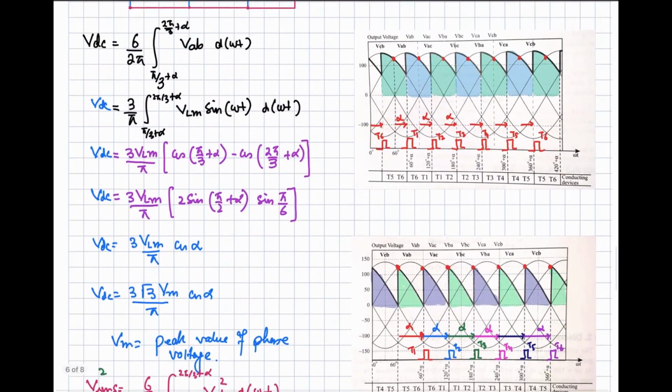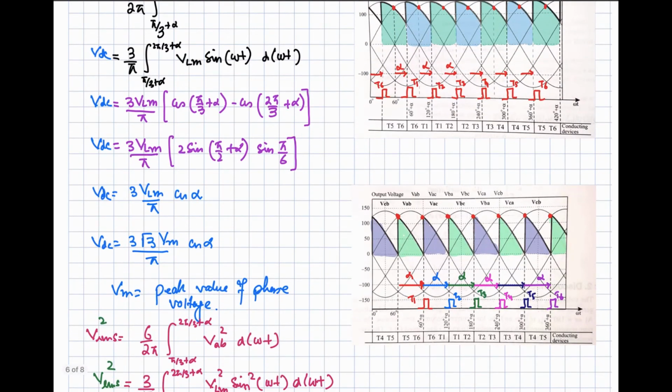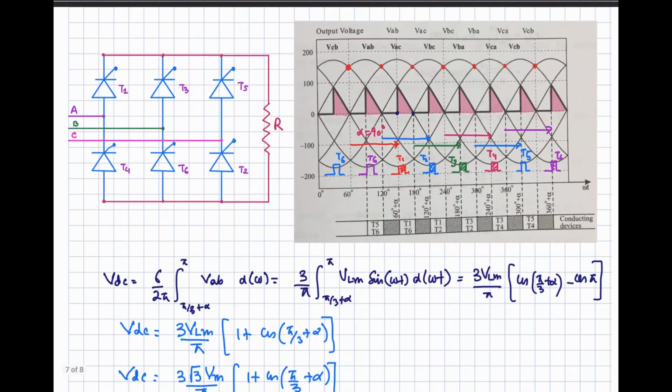Now we quickly go through the output voltage waveform at the angle of alpha, that alpha is 60 degree in this case. I'm talking about this figure, alpha is equal to 60 degree. So if you are going to apply the pulses at the 60 degree from the reference points, right? So reference points is this one, this is first reference. From here you can see the angle of 60 degree, and then for the second pulse, that is delayed by 60 degrees. So your output voltage waveform from the 3-phase fully controlled rectifier will be this shaded one.